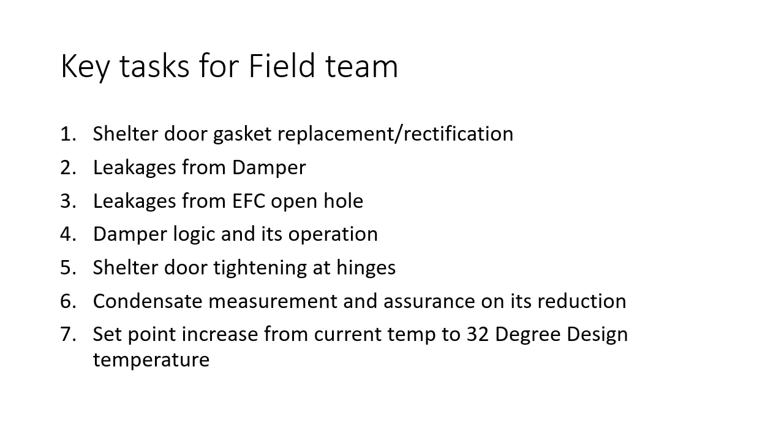Before doing this temperature increase activity, you have to ensure proper filter cleaning of active and passive components, and condenser coil cleaning as well. Tasks 1 to 6 are also applicable for NLD AG1 as well as AG2 sites. Only the set point has to be followed as per the design specification.